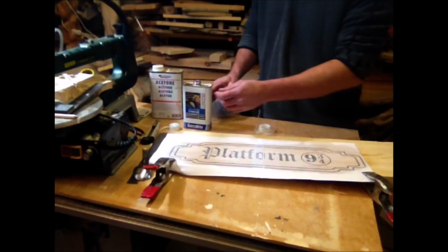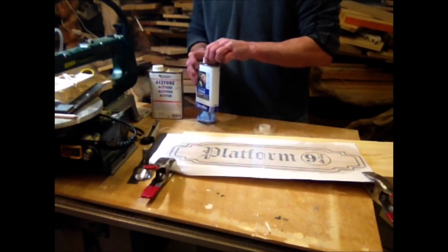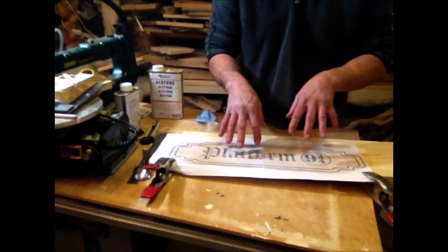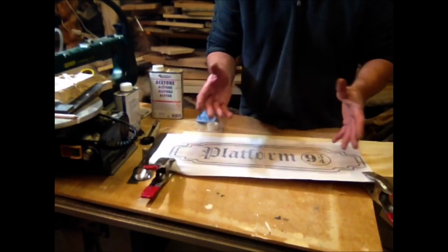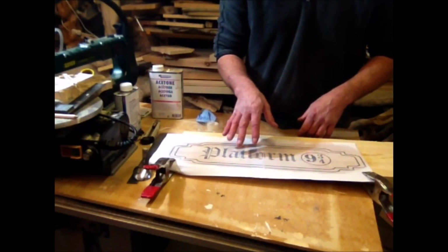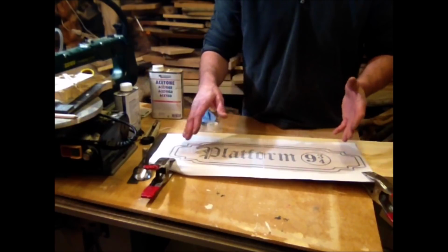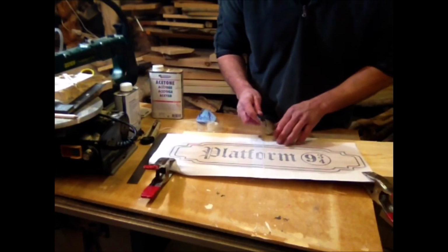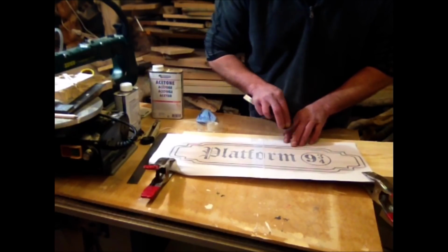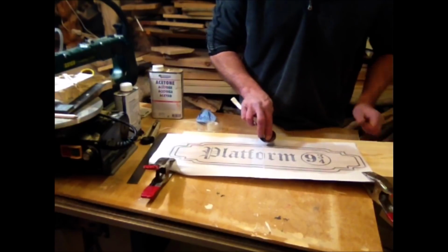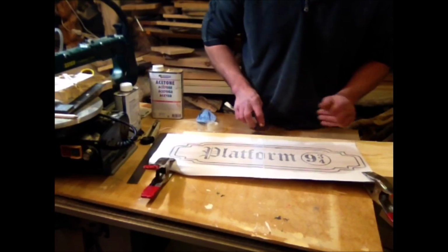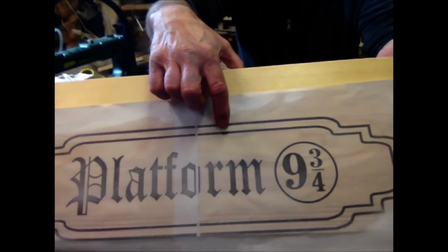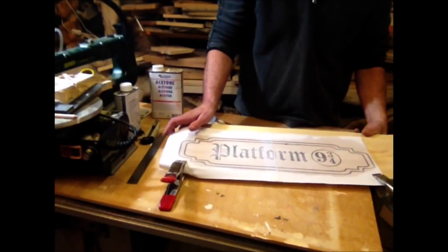Now what you need to do with this is give it a minute or so to work. What the acetone does is it reacts with the pigment from the laser printer and starts to melt it. Once it's actually made progress, we can start to burnish it off. If I start too soon, it tends to blur. Can I just give you a little example? Alright, so I've just touched there, and it's starting to blur. So just give it literally about a minute.